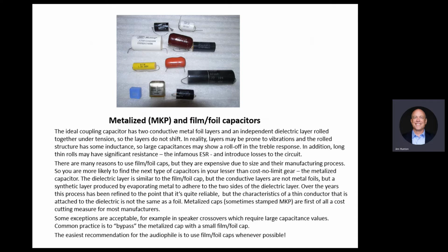There are the orange drops, the famous ones in the middle. And these two, for example, are used in AC filters. I can tell you why I brought those into the picture, because I had a circuit that uses that. And I said one day, what's this Chinese capacitor like? I broke it and measured, and sure enough, there was a metallized foil. I measured the resistance and it was huge.